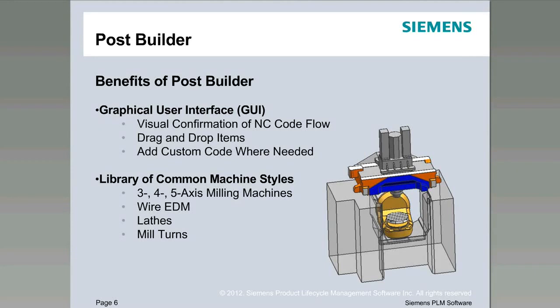What Post Builder can do. We'll talk about the benefits of Post Builder, and one of the big benefits I think of Post Builder is that it is a graphical user interface. It gives you a visual confirmation of the NC code flow. You can drag and drop items where needed. You can also add custom code where needed, so the custom code does require a little bit of knowledge of TCL or tool command language, but we have a lot of examples that are pre-built and put into the system ready for you to use.